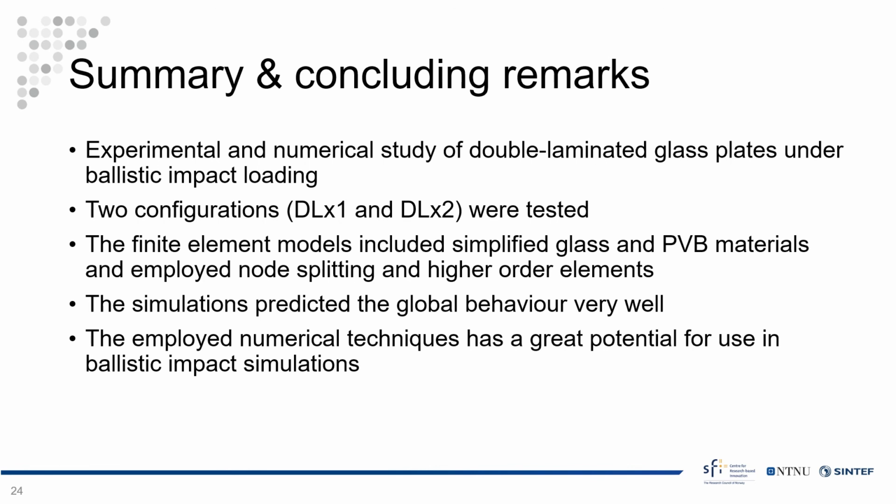So we studied double laminated glass plates under ballistic impact by both experiments and finite element simulations. In the finite element simulations, we used node splitting. We tested two different configurations, a single plate and a double plate configuration. We used simplified material and fracture models for the glass and the PVB, but we still saw that the simulations recreated the global behavior of the experiments very well. Finally, this study shows that the numerical techniques that we used have a great potential for use in ballistic impact simulations.